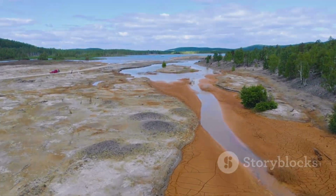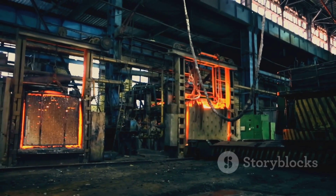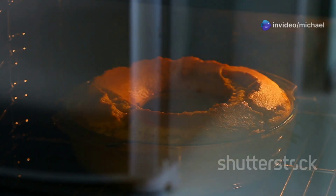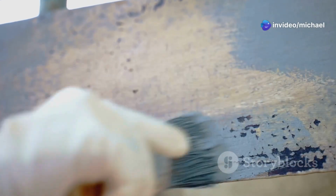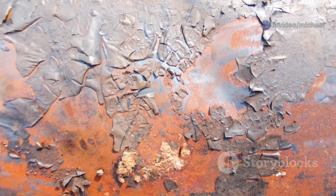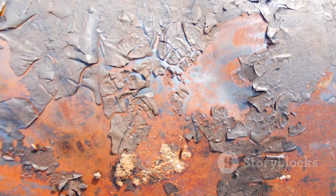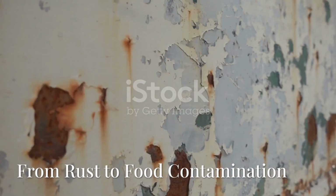Then there's temperature, too hot or too cold during the curing process, and the coating won't adhere properly. Like trying to bake a cake at the wrong temperature, it just won't set right. And let's not forget about the surface itself. If it's dirty, rusty, or not prepped correctly, the coating won't stick, leading to, say it with me, more blisters.